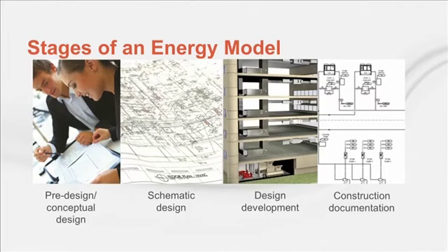During the initial phase, the data garnered during the modeling exercise, such as evaluation of site location, orientation, and building mass, can enhance the design with little to no cost. As the project goes through this stage, changes become more expensive and difficult to implement. During the design development phase, designers and consulting engineers often spend the majority of their time refining options and selections through modeling results. Fine-tuning chiller plant specifications and analyzing lifecycle costs also happen in this stage.